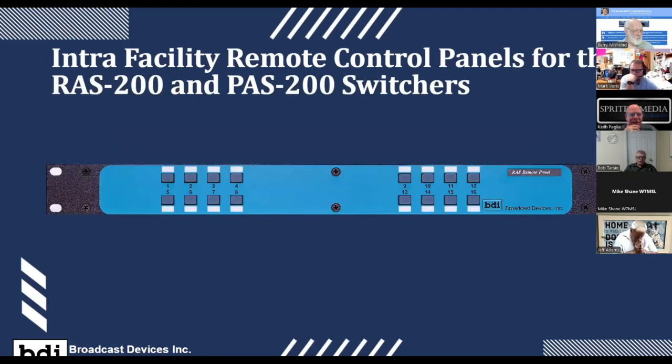And then we make an intra-facility remote control panel for the RAS-200 and PAS-200 series. On the RAS series, it works with an RS-232 protocol because that's what we use. And on the PAS series, it uses the RS-485 protocol. So both connectors are on the rear panel, and depending on which version it is, you would use one connector or the other.